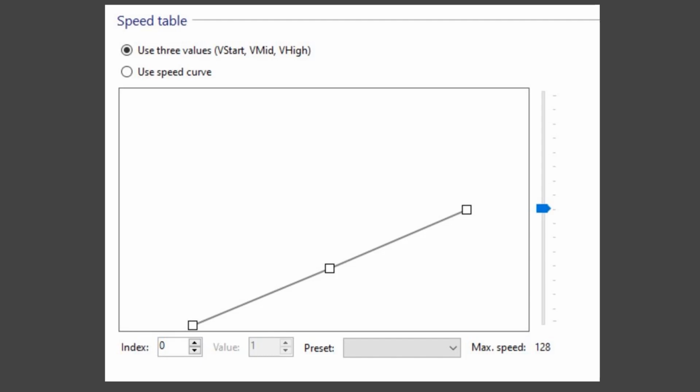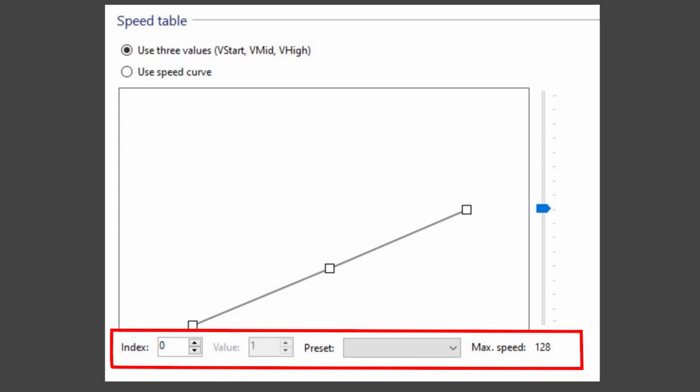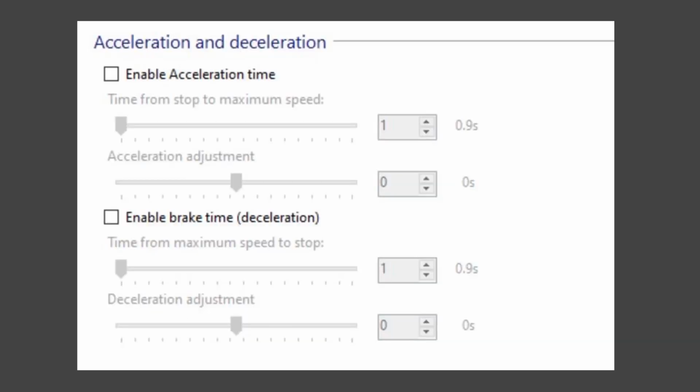Even so, this throttle simulation would work with any locomotive equipped with a DCC decoder. We really want the decoder to be custom set up for this. One of the important elements is the speed table. It needs to be linear because again, the software is calculating how fast we're going. And we only want 128 steps. We don't want the decoder to start creating hysteresis in the simulation. We also want to make sure that anything that interferes with how fast it goes or stops, like acceleration or deceleration functions, we want those completely turned off.